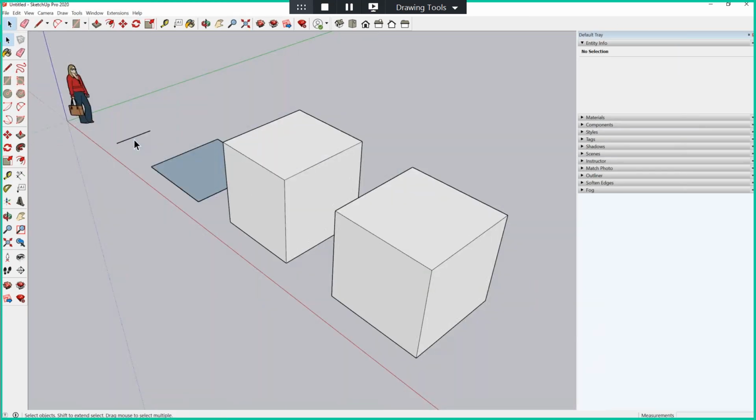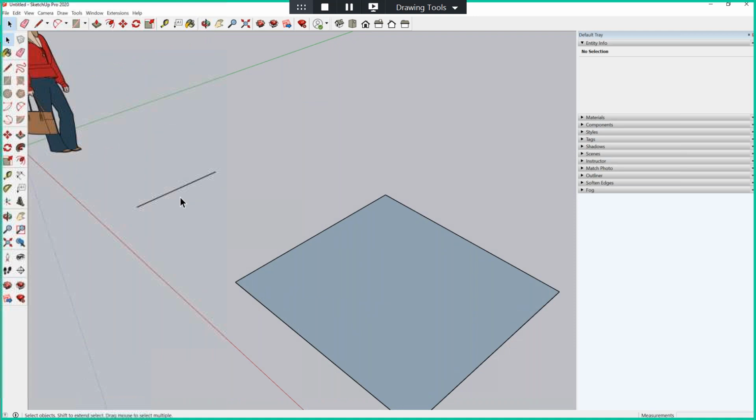Zooming into our first exercise, you can see here that we have drawn a single line, which is 1 meter in dimensions. So let's say you draw lines and surfaces and so on. If you need to change those dimensions, you can change it directly in your Entity Info panel. From here, you can see now I have set it at 1 meter. But if I need to make changes after I have done my design, you can always change it to 4 meters or your desired design intent. Okay, so moving back to 1 meter. So that is for drawing your lines.